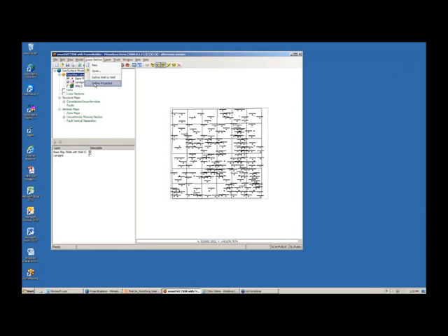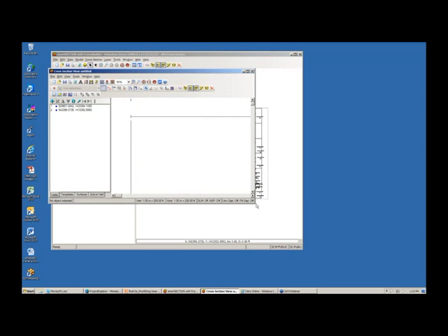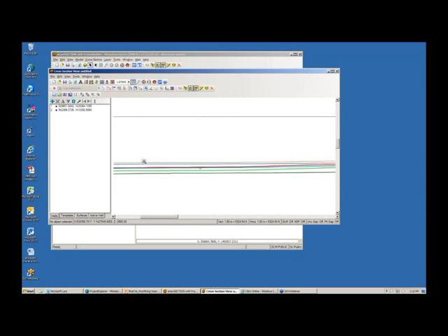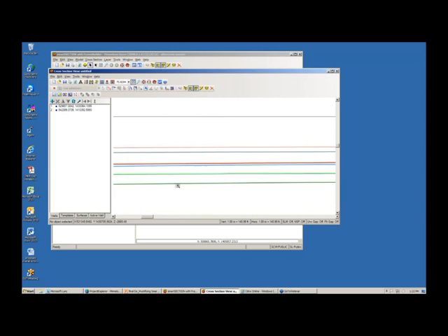So you go to cross-section, define projected, and you just go ahead and click 2 or more points anywhere across your area. Go ahead and do a right mouse button and select End Definition. Instantly, a cross-section window opens up, and I'm going to go ahead and choose the Full Extents tool. Then what I can do is come in and zoom in on my surfaces.